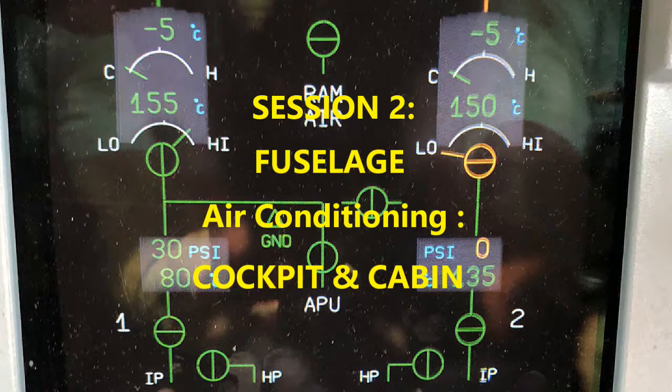So yeah, at 7,700 RPMs is what those fans are running. There's also thermo switches that are installed inside the stators of those fans. If the temperature reaches a certain level, that would be 320 degrees Fahrenheit, give or take, then the thermo switches are going to isolate the electrical supply to the fans.